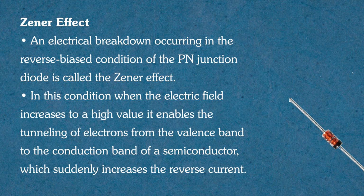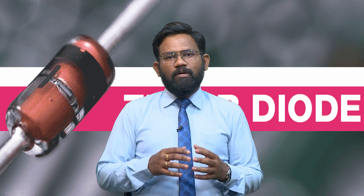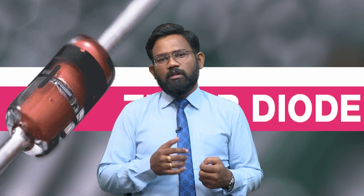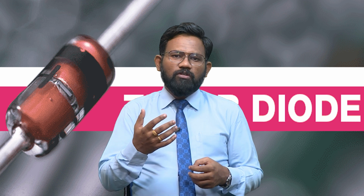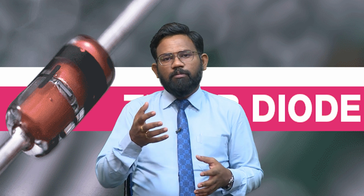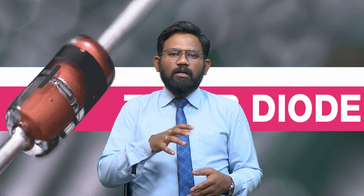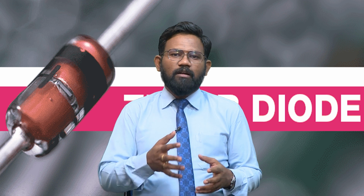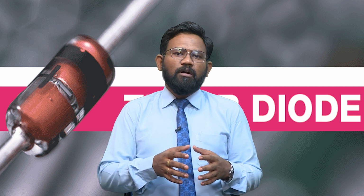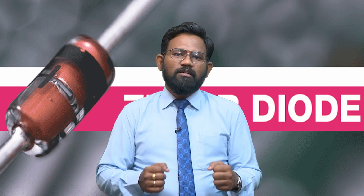Zener effect. An electrical breakdown occurring in the reverse bias condition of the PN junction diode is called the Zener effect. So we have seen the breakdown occurs in both directions, that is in the forward bias condition also and the reverse bias condition. But the breakdown which occurs in the forward bias condition is called breakover, and that breakover voltage is noted. But in the reverse bias condition, the electrical breakdown that occurs is called the Zener effect, and that condition of the PN junction is called the Zener effect.